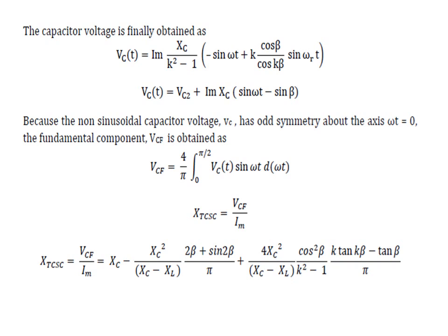So in order to avoid the resonance condition, what we have done is we turn on the thyristors in odd time, that is T1 and T3, and we turn off the thyristors for even time, that is T2 and T4. So we have alpha and beta angles, that are nothing but conduction angles. If you control the conduction mode, indirectly we are controlling the turning on and turning off of the thyristor, and thereby we are controlling the current flowing through the capacitor. That means whatever capacitor voltage is developed will be directly dependent upon the thyristor conduction mode. So all these equations mainly give this brief idea.